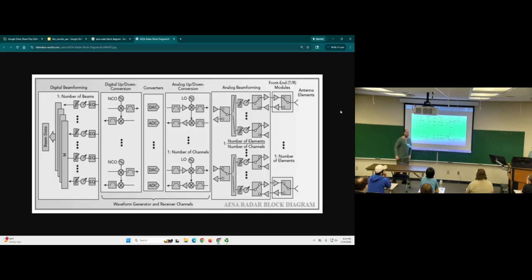So you're doing frequency modulation with the carrier wave when you're sending it out and producing it? If that's your purpose, yeah. You'll do that in the signal. The modulation almost has nothing to do with the radar part of that. That's a part of it, and you should modulate, because if you're just sending out sine tones, you're hilariously easy to jam, because that's very easy to replicate. There's a whole thing about what are called jam-resistant waveforms. That's a whole classified concept, but it means fancy waves that you can't easily copy and send back to jam them.